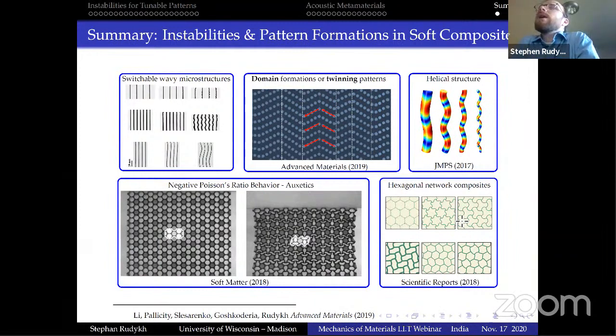It is correct that the machinery of the instability analysis that I'm using is actually built on periodicity, and I probably misinterpret the question about randomness. Rather, looking into post-buckling analysis, I can add imperfections in whatever shape and form as random ones and see how that manifests in the actual post-buckling behavior.